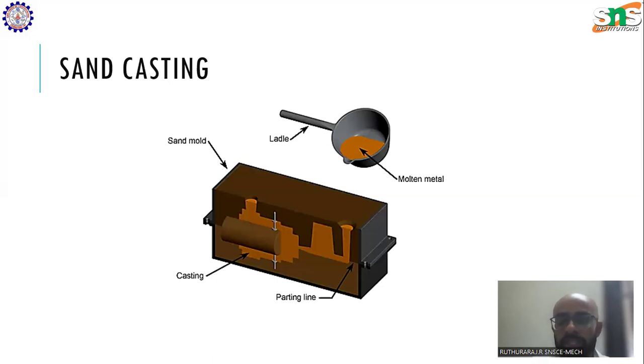Flowability means it can be easily transferred from one place to another, and it can be easily placed or stored without any formation of blocks. But clay has very good moisture retention capacity and it can be easily molded into any shape. The drawback of clay is that it is not flowable compared to sand. So to enhance that flowability, we use river sand. Similarly, river sand, though it is flowable, cannot be made into shape as readily as clay. So by combining these two, you get the better properties of river sand as well as clay.